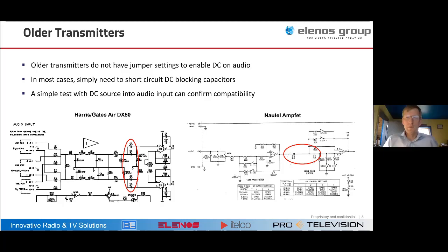Yeah, I agree with what Rich is saying, but if somebody wanted to try it, as long as the DC of the carrier and the audio are coming from the same place, the DC parts of the envelope essentially is plate modulated. If they're coming from the same place, it should be doable. Your audio input brings the carrier to zero normally, right?